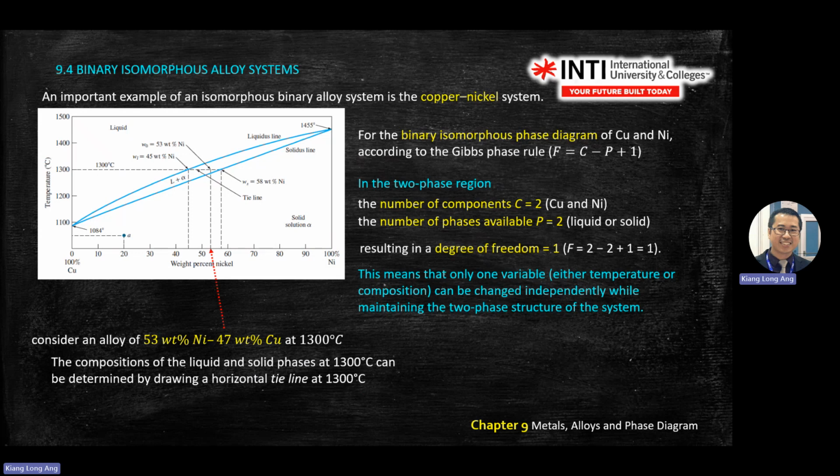It's actually finding a ratio, of L and solid, or you can say A and B. You have a total, right? Total is A plus B. So you want to find the ratio of A, so A divided by A plus B. Okay, but there's a trick there. The trick is that if you're finding somewhere here, you're actually using the other side. Let me show you what it means.